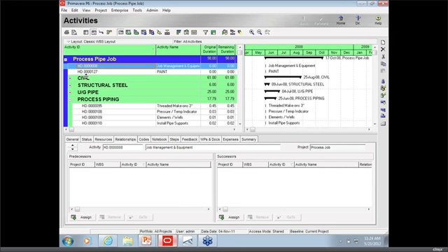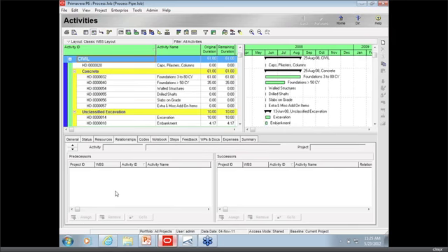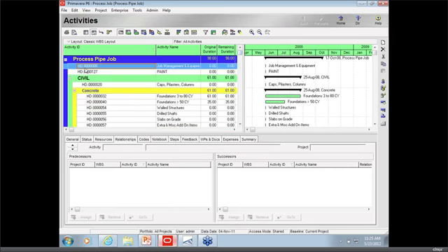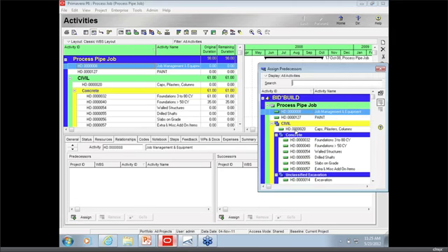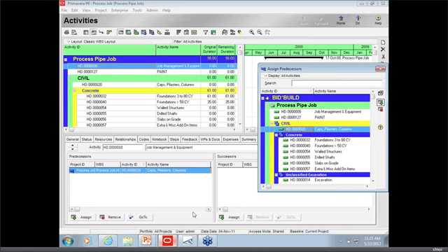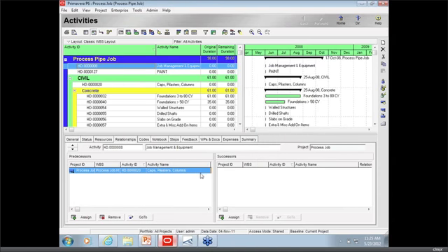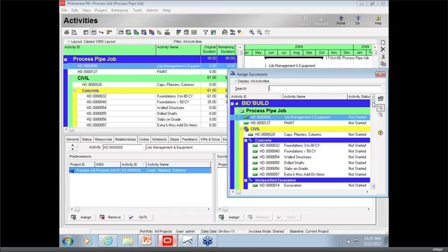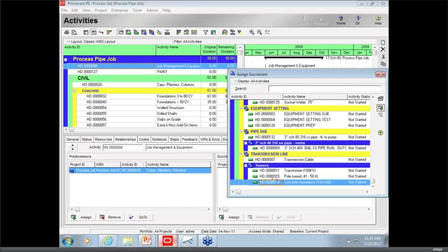As I showed on the estimate, there's currently 0 duration and cost being generated. Well, I want the cost on the hard dollar side again to be driven by the schedule. So however long the job is, how long we need to pay that project manager and operating engineer. So the first thing I'm going to do on the Primavera side is establish some relationships. So for my predecessor, I'm going to pick this very first activity under civil and add that as a predecessor relationship. And for my successor, I'm going to select the last activity in my schedule.